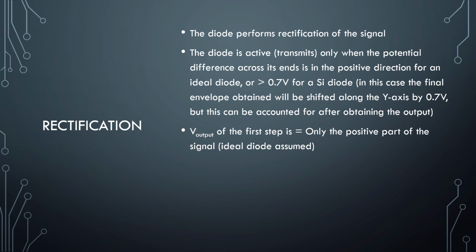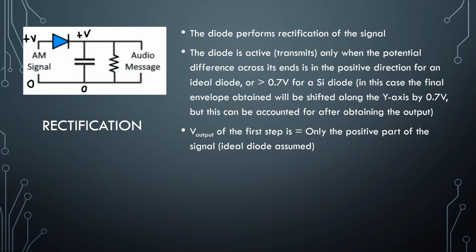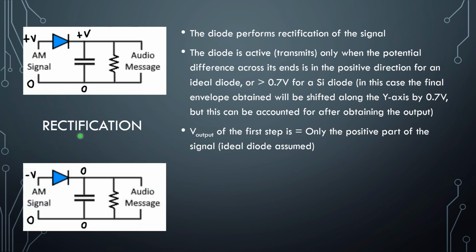For example, in an AC RC circuit, the voltage only gets phase shifted. Assuming that the diode is ideal with zero cutoff voltage, the voltage across the capacitor is V input when V is greater than 0, and the voltage across the capacitor remains 0 when the V is less than 0 in the input signal.